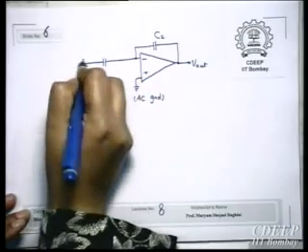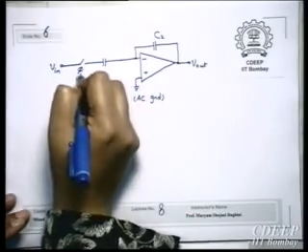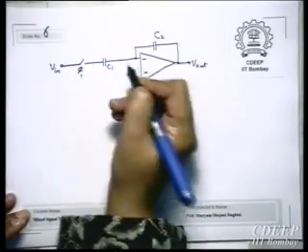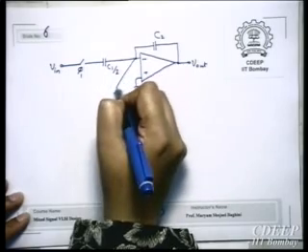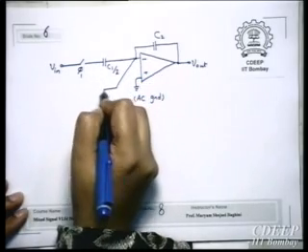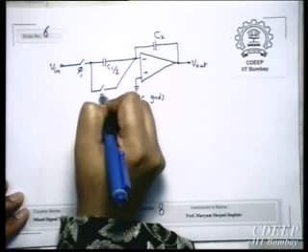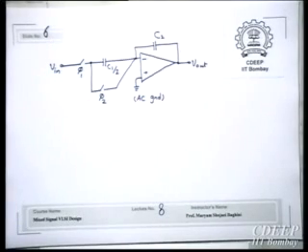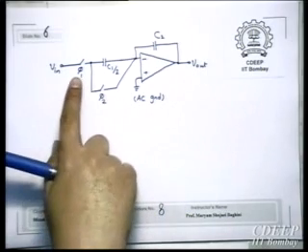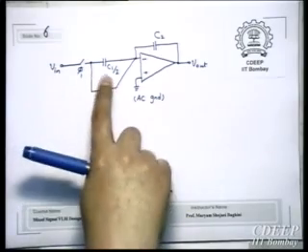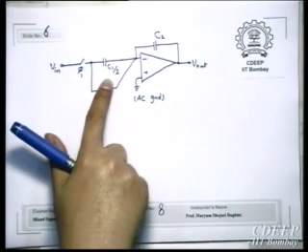We put a capacitor with a switch. Okay, so this was as before, phi 1, and this was C1. Now we want to make average. We make it C1 upon 2. Okay, and again we discharge it in phi 2. So what to do to make it average? What we want to do, in first phi 1, when this switch is closed, we don't want the entire charge to go here. We want half of it to go. That's why we make it C1 upon 2.